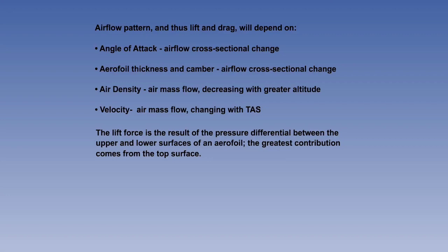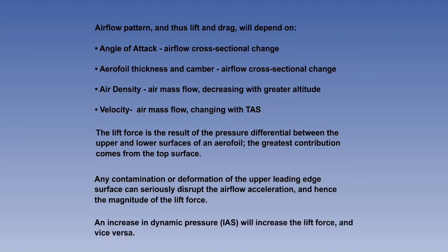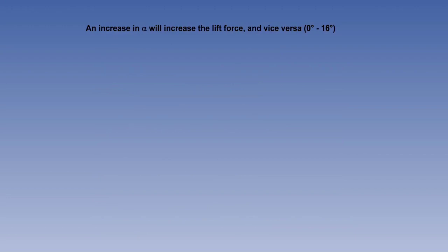The greatest contribution comes from the top surface. Any contamination, particularly ice, or deformation of the upper leading edge surface can seriously disrupt the airflow acceleration, and hence the magnitude of the lift force. An increase in dynamic pressure with indicated airspeed will increase the lift force, and vice versa. An increase in angle of attack, alpha, will increase the lift force, and vice versa, over the normal flight range of 0 to 16 degrees.